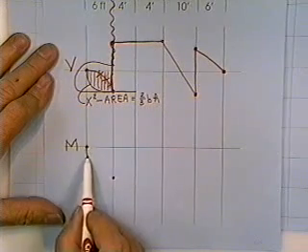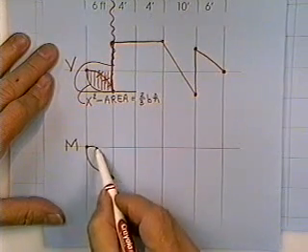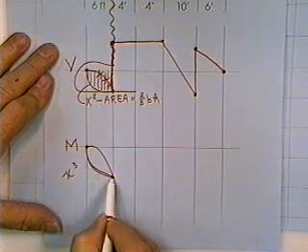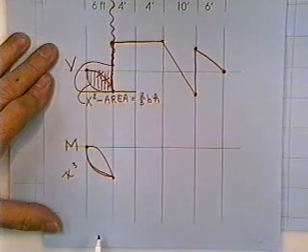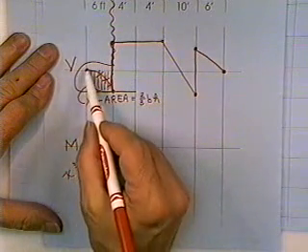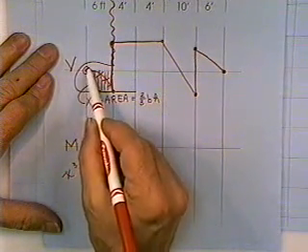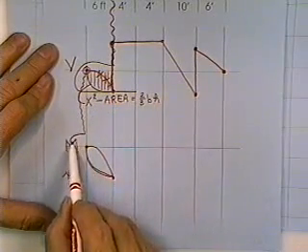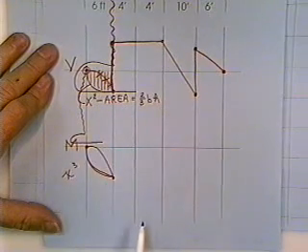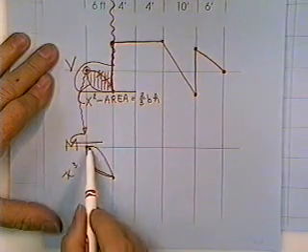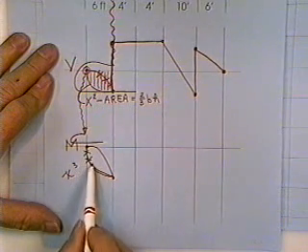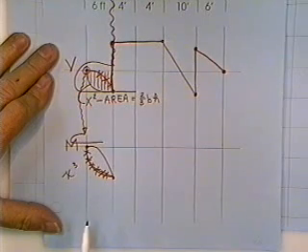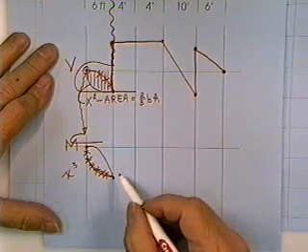The curve is a cubic. It's either this one or the top one. I go to the 0 end of the shear diagram's value. I come straight underneath that part and insist that the diagram have no slope at that point. That says the top curve is the proper curve. That little rule, that the value turns into slope, is very, very valuable.